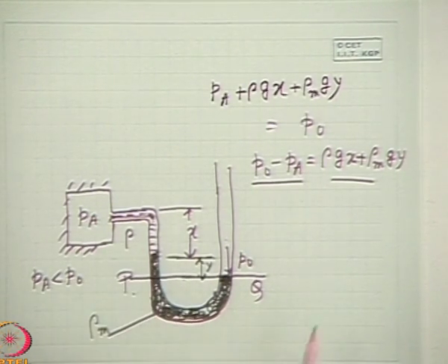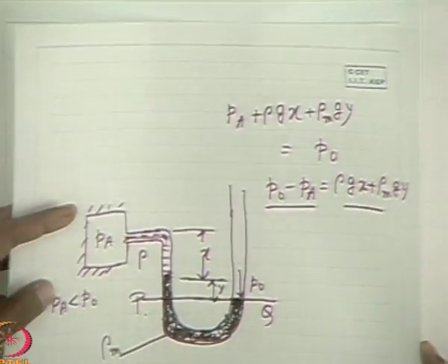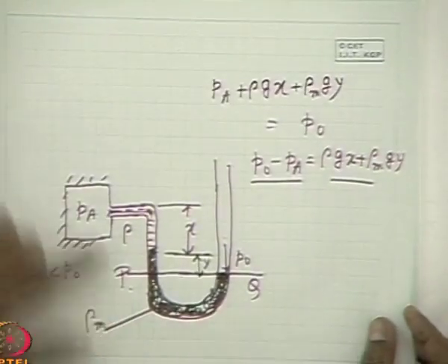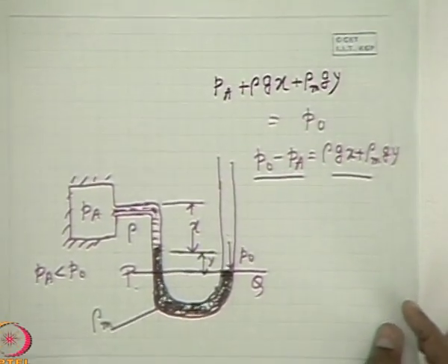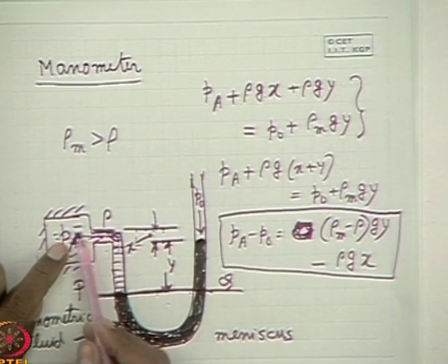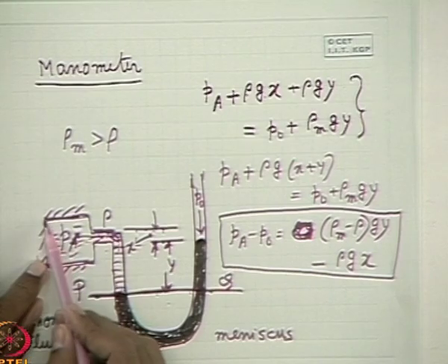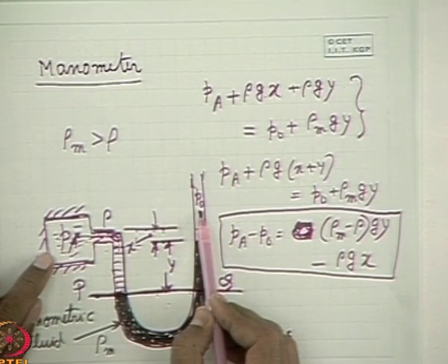This thing settles like this. Now, after that I would like to discuss how to find out the difference. You see, in all the cases, a manometer always measures the difference in pressure. Though we say we are measuring the pressure of this system, it is the pressure of the system with respect to atmospheric pressure.